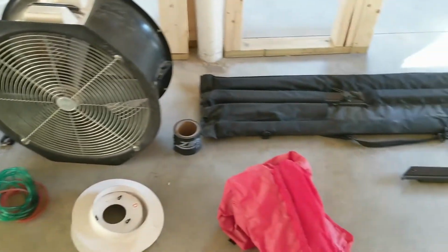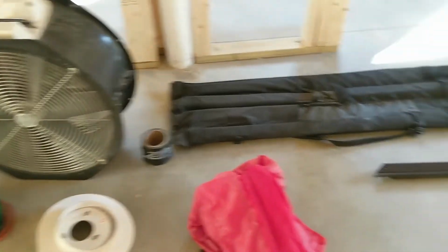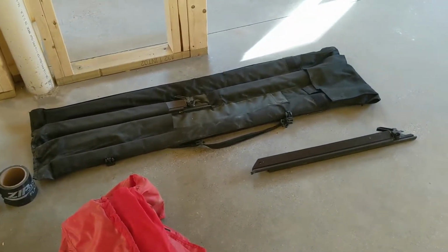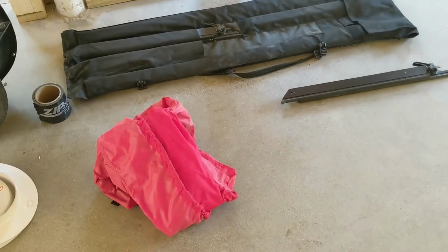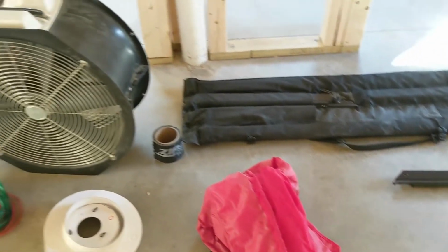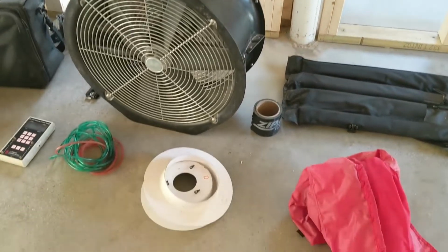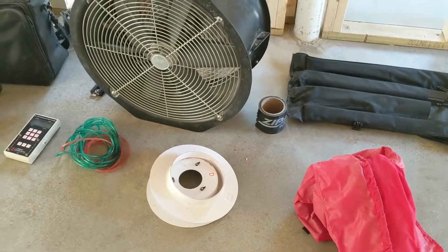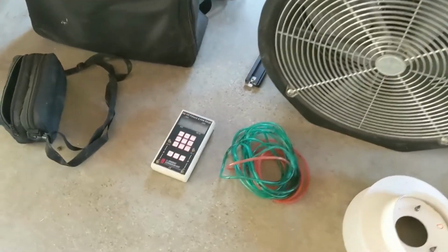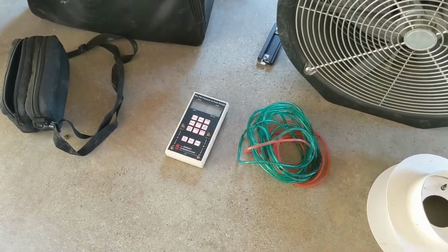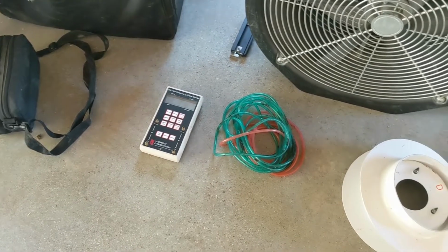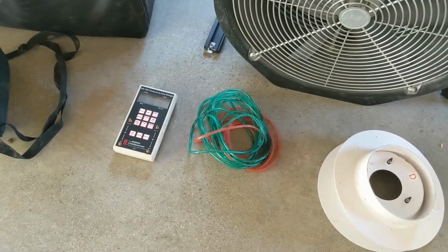So here we've got the parts and pieces of the blower door set up. We've got the frame. I'll pull those parts and pieces out and assemble the frame. There's the shroud that creates the seal at the opening. We've got the fan itself and some different rings for closing down the airflow. And then kind of the heart of it here is this manometer, this thing that looks like a calculator. That's going to be measuring the airflow. And there'll be a tube attached to the fan and a tube that goes outside.